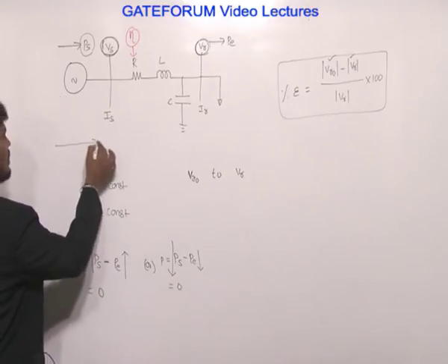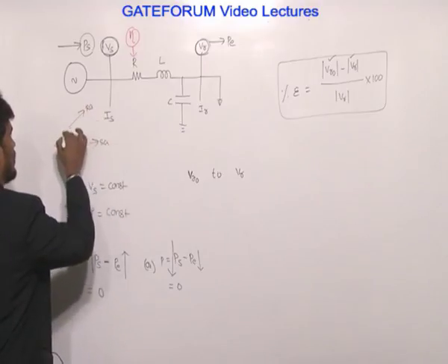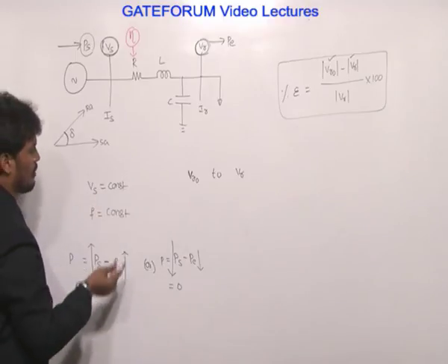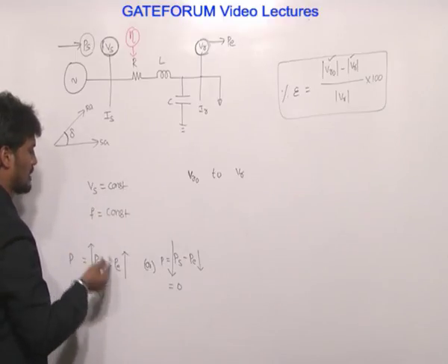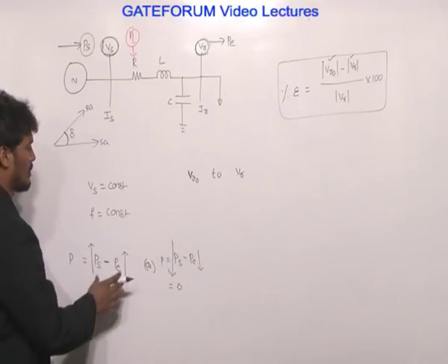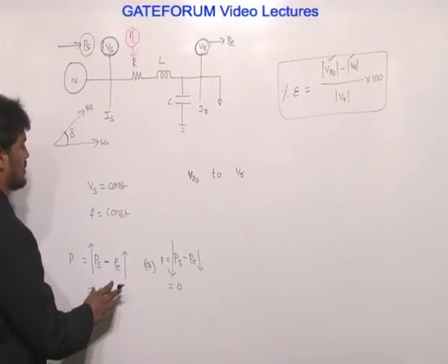This is the synchronous machine. This is the rotor axis, and this is the stator axis. The load angle is delta. As electrical output increases, mechanical input increases; as electrical output reduces, mechanical input reduces. Therefore, we maintain balance between mechanical and electrical, and power loss is 0.